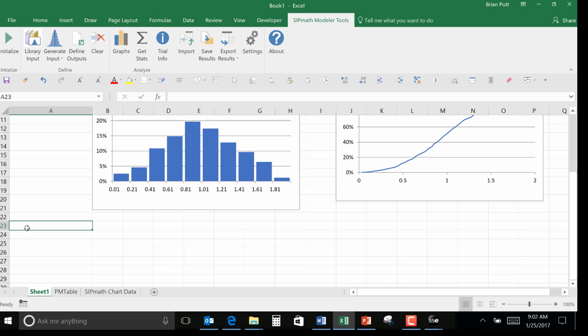Let's do a normal distribution here. And for the normal, we're going to need a result, we need a name, we're going to need a mean, and we'll need a standard deviation, and we'll have our seed over here. So let's do a mean of 3 and a standard deviation of 3. And there is a reason why I want to use those values. That'll become apparent as we move on here. So we need a seed, so we'll just put 100 here.